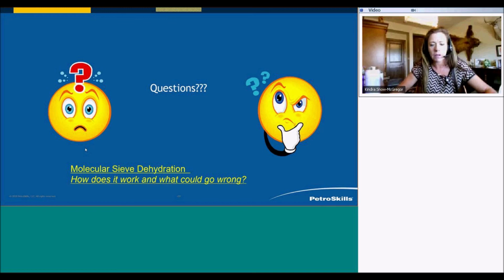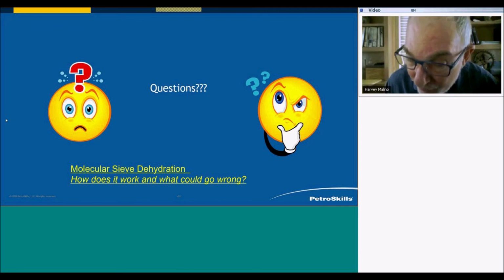Sure, that sounds excellent. So the first one, this is a good question, Harvey. Someone would like to ask about changing an original project which was originally designed for 4A sieve. What are the important variables to consider when you evaluate doing that change out besides the thermal demand or the temperature? Is there anything else they need to be aware of or check? They want to change out from 4A to a 3A.